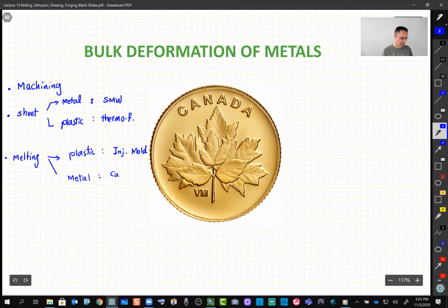With casting, we learned that we have three choices, and basically those are the mold. So we can have a mold made out of sand, or we can have a mold, which we call a die, for die casting, made out of metal. So die casting, or we can make the mold by using wax and ceramic.